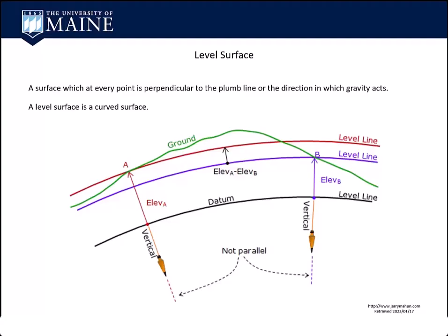There's a datum. That's something we'll talk about a little later. That's the reference plane that you're using. It could be anything. We'll look at datum planes a little later, but every elevation is connected to a datum. It could be an established datum nationally, it could be a local datum, or it could be an assumed datum. But somewhere there's a zero.